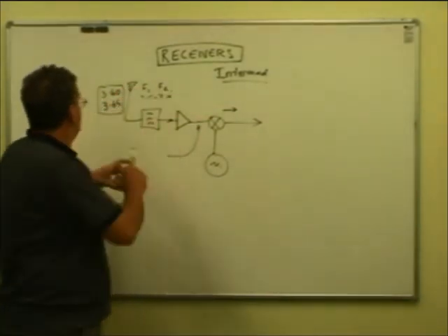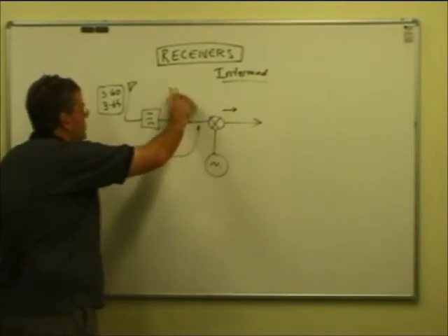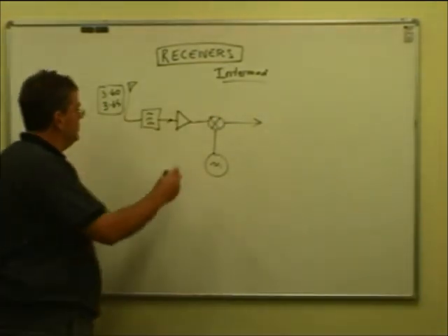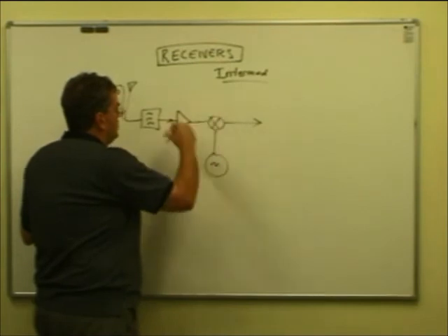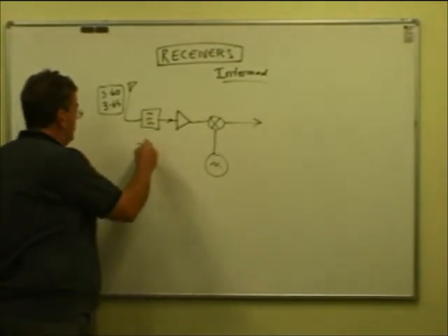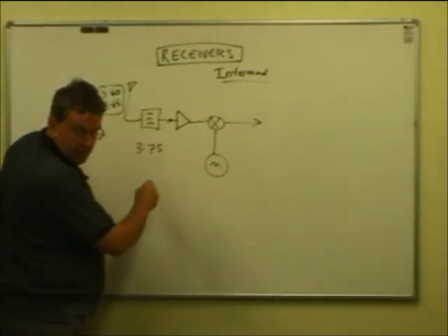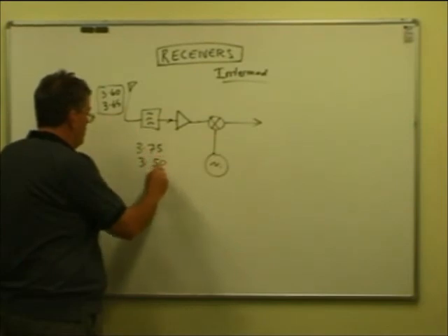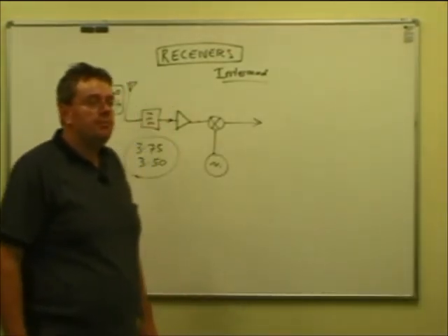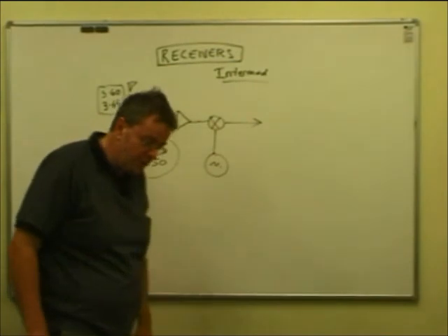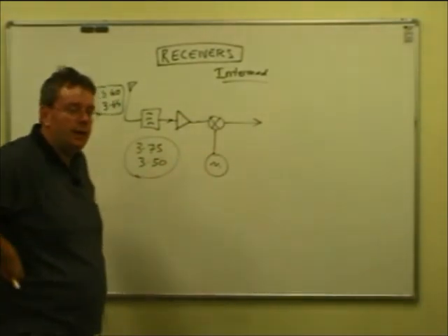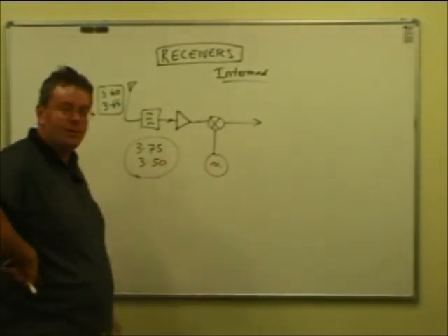If we've got very, very strong signals on those two frequencies coming in, just for example's sake, and our receiver is not particularly well designed, this combination will create two new signals out of the blue on 3.75 and, I had to work out the math, 3.5. You could actually do this on older radios, especially things like the Yaesu FT101s from the 70s. Not picking on it in particular, but its front end, especially the early ones, was not particularly robust. In other words, it couldn't cope with strong signals very well.